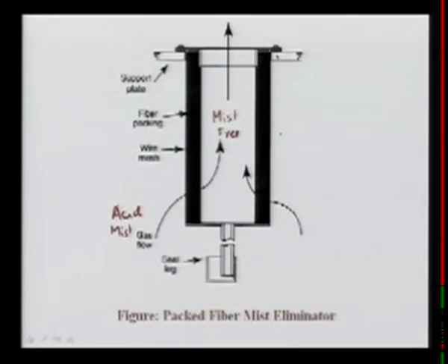Very quickly, it might be a good idea to give you a little feel about the SO2 emissions and the conversions. Suppose the SO2 to SO3 conversion is, let's say, 90, and here are the SO2 emissions. If only 93% conversion is there, emission is around 48, and this quantity is in terms of kg of SO2 per ton of acid. And suppose you are converting, let's say, 94, then the emission could be around 41.